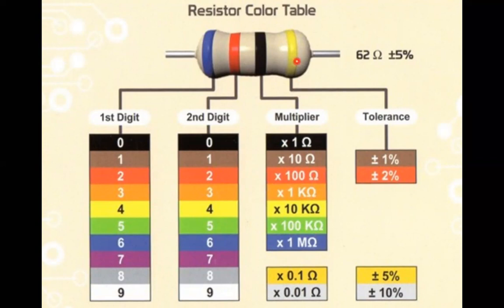Opposite to this gold or silver, we have to measure the resistance value, taking the strips into account, and the strips are made of different colors. How we have to remember, I'll show in the next slide. So this is the first digit, the second digit; consecutively we write the first number and the second number, multiplied by the multiplier of the third color code.